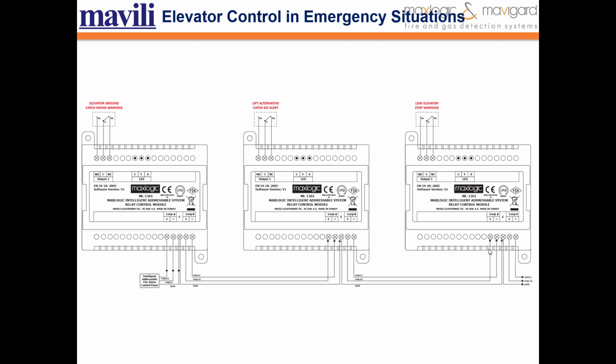The sample application image shows 3 relay control modules connected to a loop line in addressable system. Each module is connected to the relevant relay outputs on the control panel of the elevator, so that signal is sent to these relay outputs in case of fire. Output contact capacity of relay control module is 30 volt DC and 1 amps.